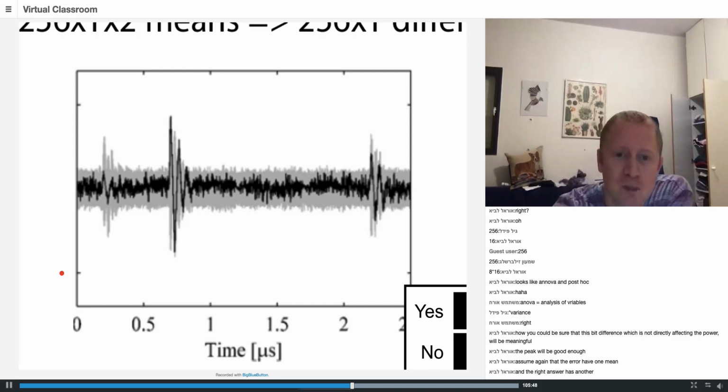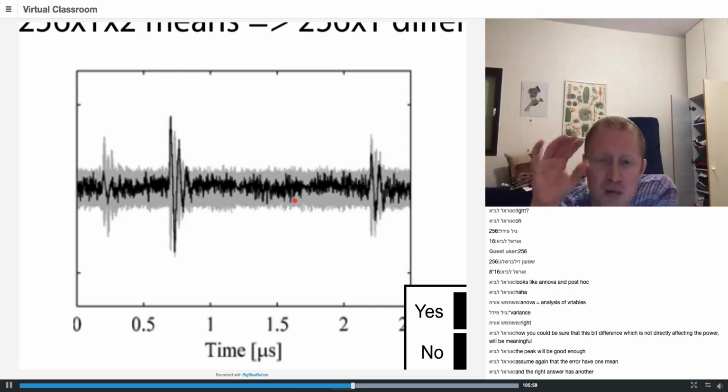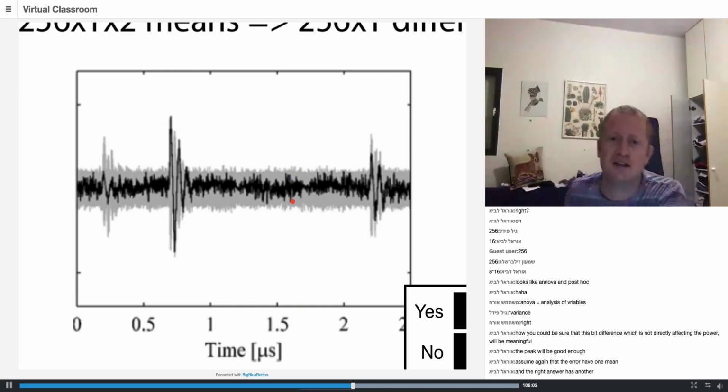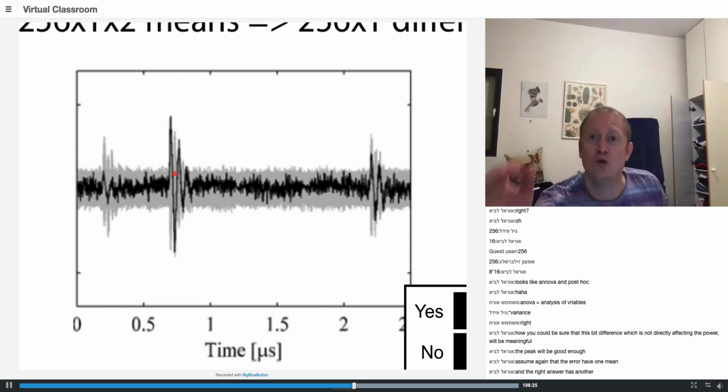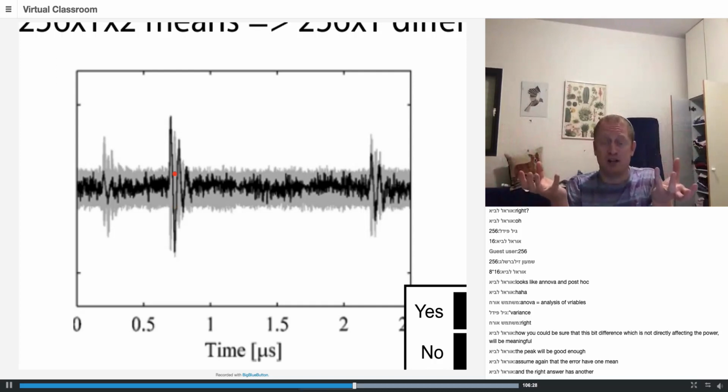And now looking at the figure, you see that most of the time we get a very, very small difference of means. This is the sum of many, many random variables, so they really tend to stay inside this area around 0. So this is measurements of 0 with noise. The difference of means effectively is 0. But you see that for the correct key, there is an area where you have a really, really significant difference of means between the 2 bunches of traces which I created.